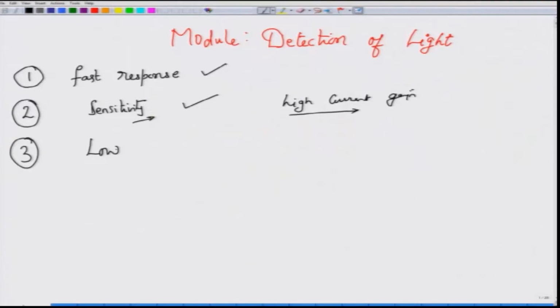So one of the characteristics that you want from a photodiode is that it must add very little noise. So low noise is one of the important criteria from the noise perspective, because if my photodetector adds very low amount of noise, then I will be able to take the optical signal at very low powers, yet I have sufficient signal to noise ratio at the output in order for me to detect information sitting in my desired signal.